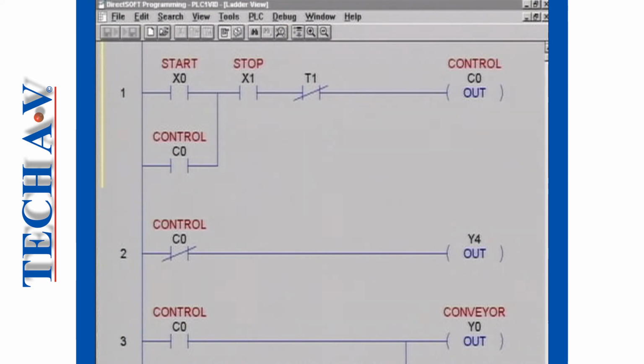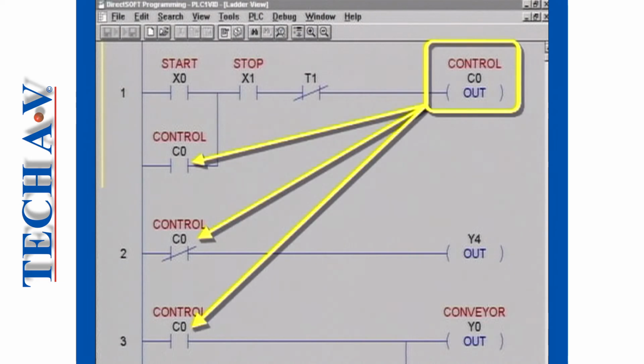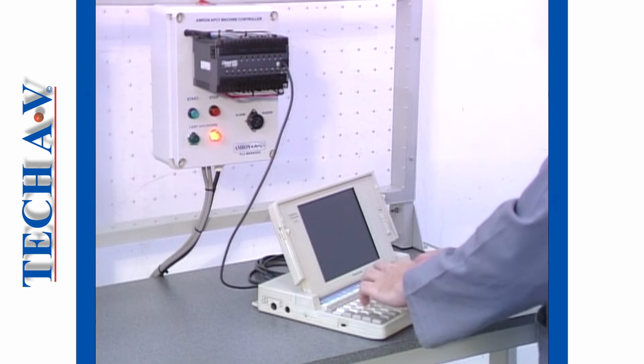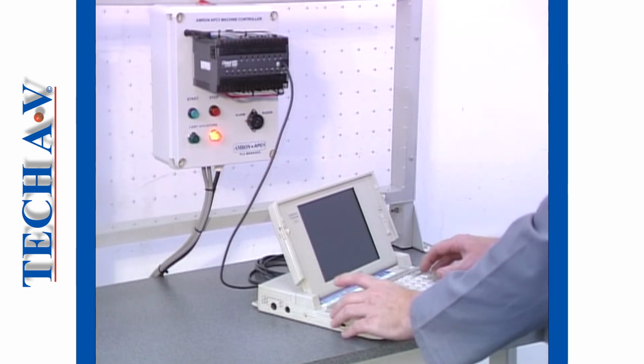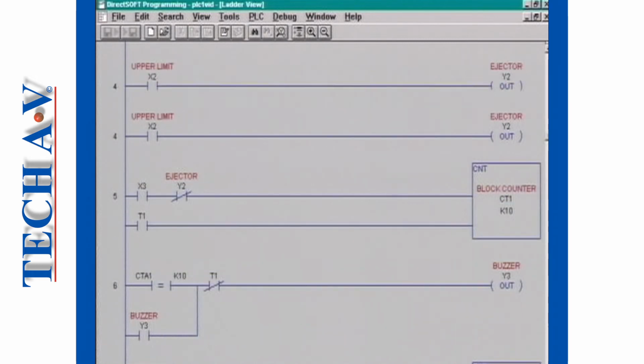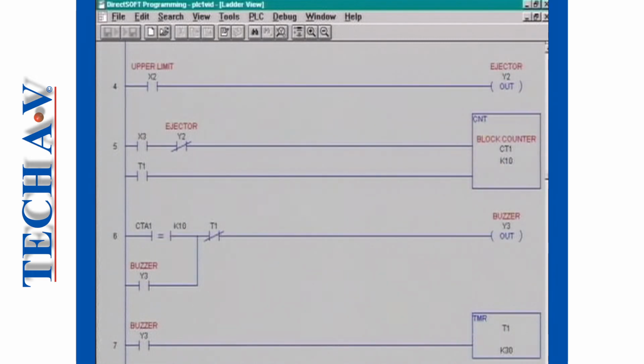And the PLC can use the same device at many different places in the logic to accommodate different system requirements, because each input and output has its own unique address location. This is where we find the big differences between PLC and relay logic control systems. Although programming styles do vary amongst the various PLC manufacturers, there are two important points that all PLC logic has in common.